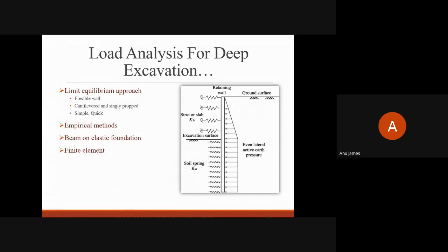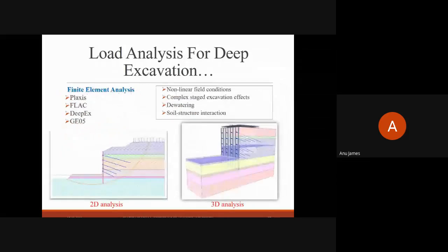Next is the widely used finite element method. Different softwares are available for the analysis of deep embedded systems using finite element analysis, such as Plaxis, Geo5, etc. All these can be used to simulate any proposed deep excavation problem. The advantage of the finite element method over other methods is the different modeling possibilities.